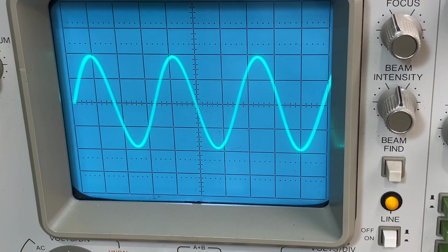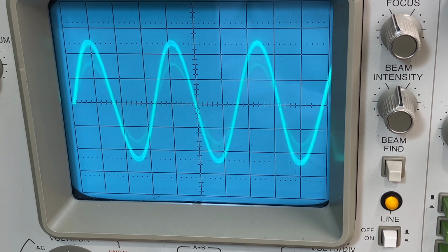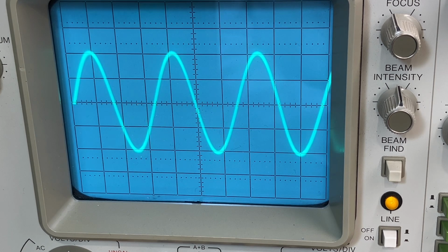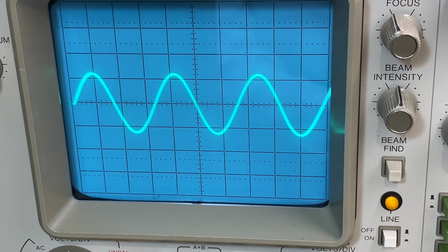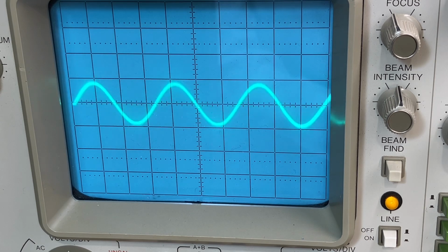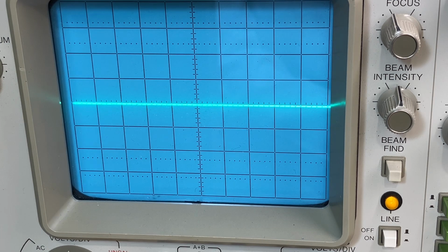All right, look at that. It looks like a sine wave to me. How about that? You can adjust this little trimmer resistor. You see if I can do that here. As you decrease the resistance, the amount of negative feedback increases, which decreases your amplitude until you have so much negative feedback that it stops oscillating altogether, like right here.